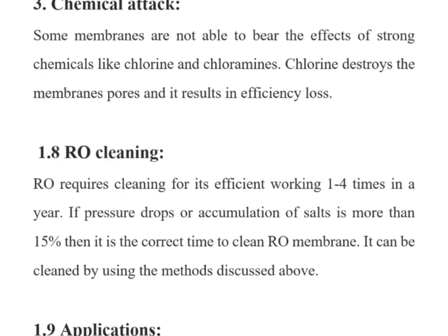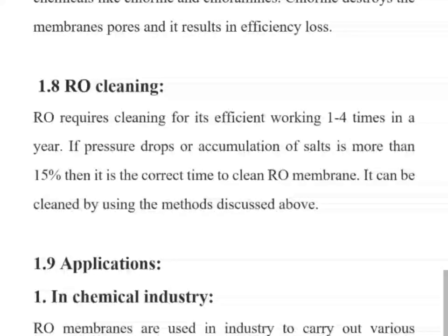Next is RO cleaning. How can we clean our RO membrane? For the efficient working of RO membrane, we have to clean it 1 to 4 times per year. If pressure drops or accumulation of salt is more than 50%, then it has to be cleaned more rapidly.